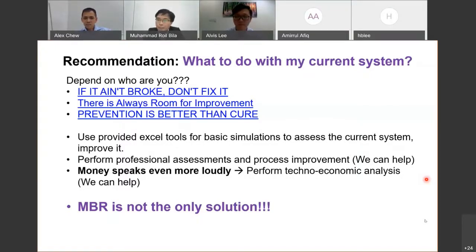I have no direct experience treating, I think this is laundry or detergent wastewater. Because we have to distinguish between what is the source of the TOC. If all of your TOC is coming from the surfactants, then we need to customize the MBR. We have to go for a tight microfiltration that can retain the surfactants inside the reactor while they are being biodegraded by the microbes, and can have surfactant-free effluent.